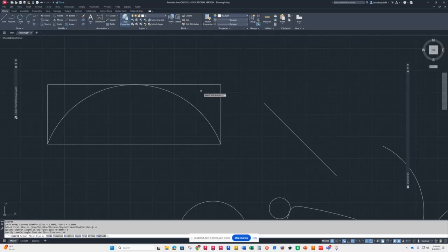All right, so then I would have to think which side needs to be at 30 degrees and which side isn't. So let's say the vertical side is not the one at the angle, and then I click on that. Click on the top one, so now there's my 30 degrees on vertical. If I do the same thing, and I pick the horizontal first, and then pick this one, then it's off the horizontal.